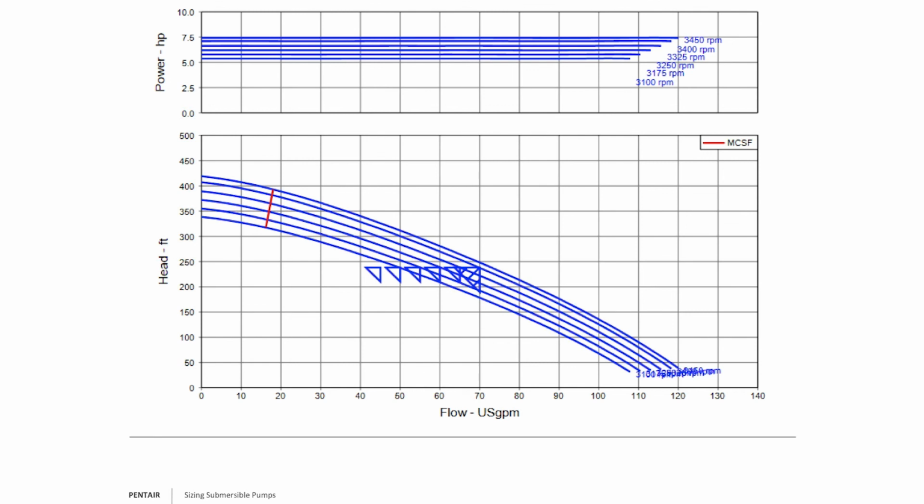Now, the other thing I'll point out in this curve, if you notice, it doesn't have the best efficiency point or an efficiency curve. Because here we assume 70 gallons per minute is the best efficiency point. A lot of smaller pumps don't have efficiency points necessarily drawn out or a curve for the best efficiency, nor does it show net positive suction head required. Because typically when you're talking smaller pumps, the atmospheric pressure of 25 feet will satisfy that, so you worry about submergence. When you don't see a submergence listed, like in this curve, then always assume 25 feet. So there's your power consumption curve.